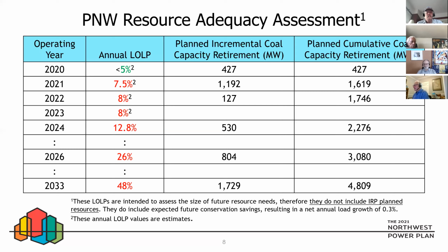And by that, I mean that in every single case for climate change, with increasing temperatures, it's very intuitive. With increasing temperatures, even if the precipitation is exactly the same year after year, you would expect that during the fall and winter, you would get more rain and less snow with higher temperatures. And so you would expect on average that the river flows would be higher in the fall and winter. Because then you have less snow and less of a snowpack, you would have lower flows in the spring and summer. It's not always the case. These downscaled data provide a wide variation, and that's another presentation I could make, a very wide variation of possibilities.